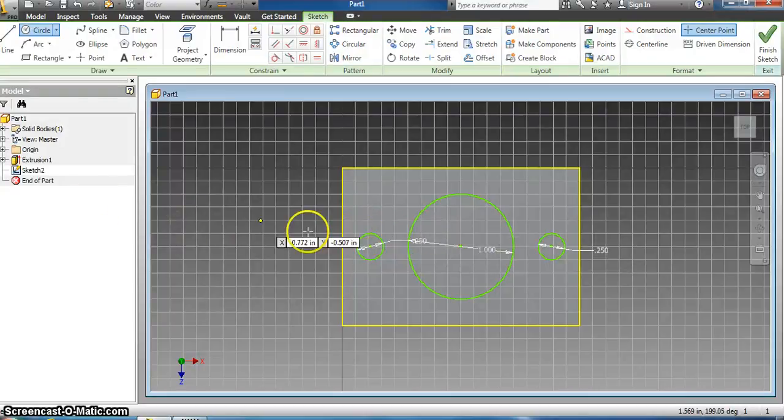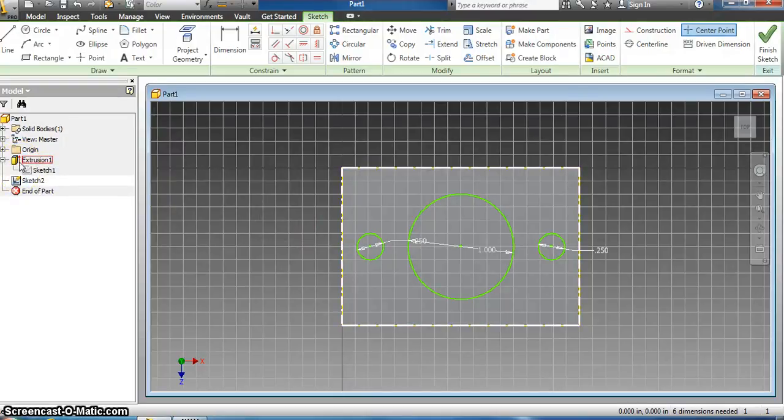To show you what happens, once we created that second sketch, you can see now we have our second sketch here, sketch 2, which has the circles associated that we drew on. I'm just going to press escape to go back to my cursor. Once we created that extrusion with the first sketch, it basically dropped that. Here you see sketch 1. If I click that plus there, there's the extrusion that we put on sketch 1, but sketch 1 is there. It's in a hidden view right now.